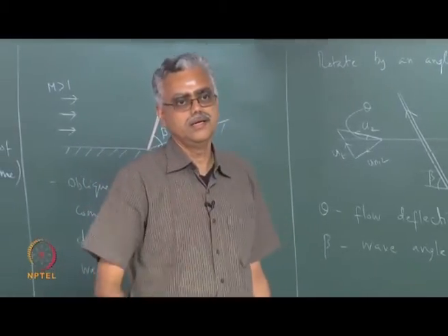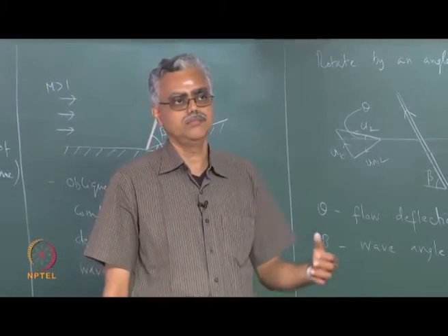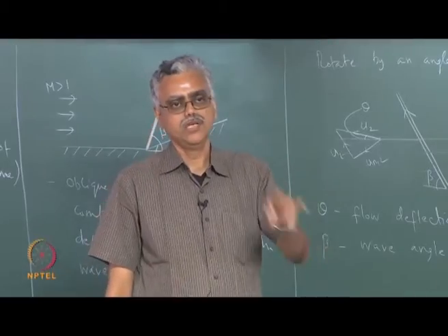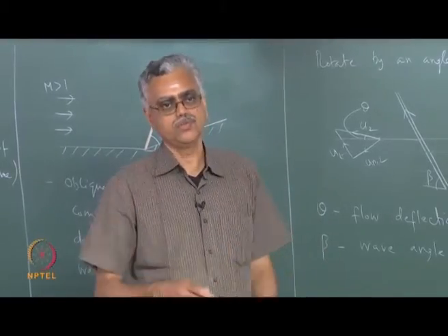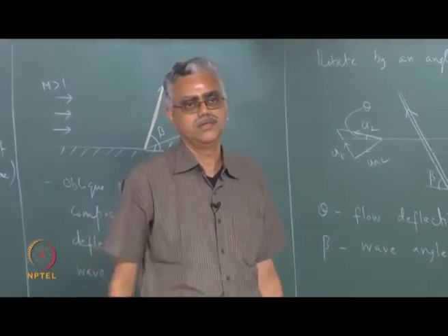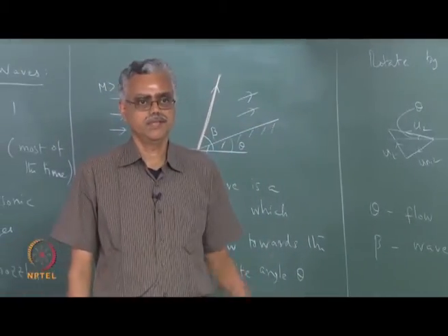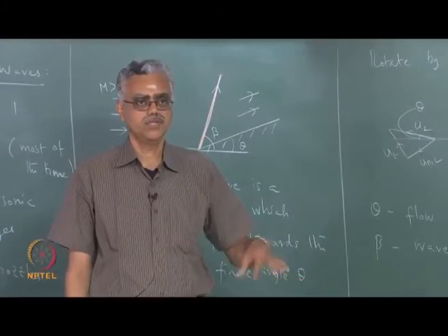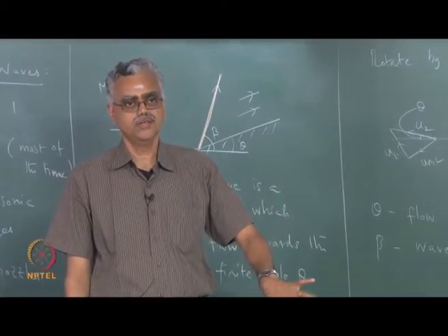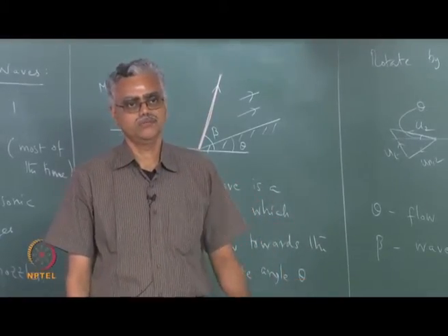It has to be either an expansion process. You cannot have a compression process where the flow is subsonic and it is compressed further. The shock wave always moves with supersonic speed in a quiescent medium, which is why the flow always approaches the shock wave with a supersonic Mach number.